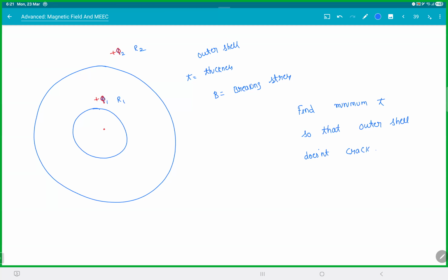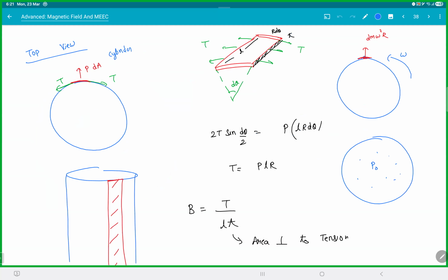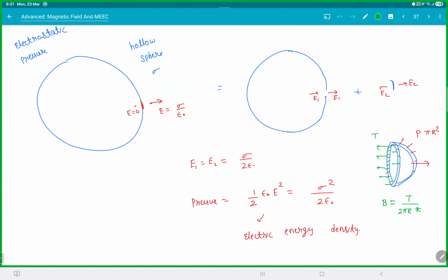So get the pressure on the outer surface. That's the fastest way. Because if you get the pressure, then you can use the projected area. This thing, pi r square, is the projected area. This is there in the fluid mechanics notes. In case you have no idea what it is, you should definitely check out the notes. What an important concept. It comes in 5 to 6 different chapters.